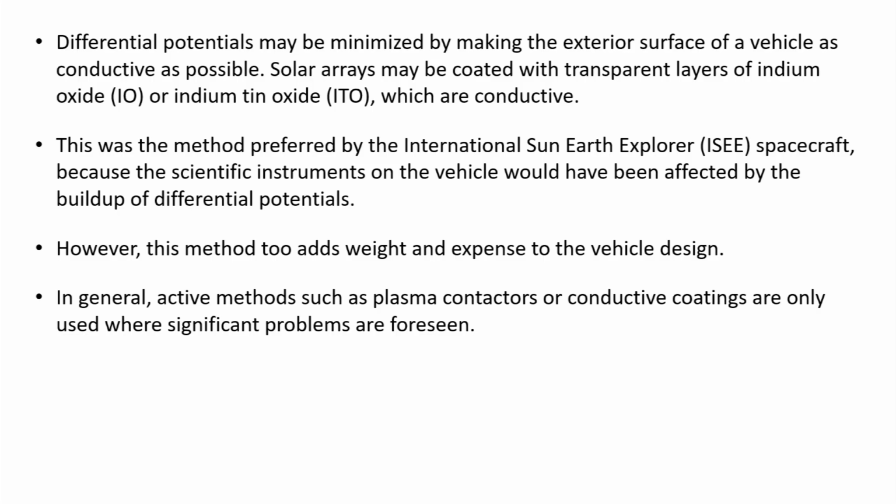For low Earth orbit, the effect of spacecraft charging is much more benign. As we already discussed, it can be minus 100 volts, in some cases minus 400 or 500, but that will not give rise to a discharge. Generally, the discharge effects occur in high Earth orbit when a magnetic storm occurs.